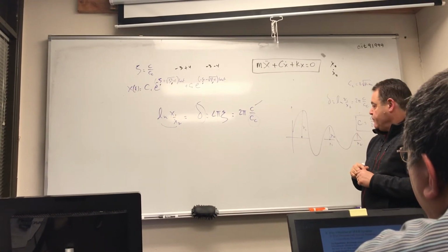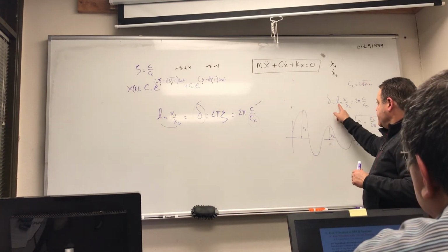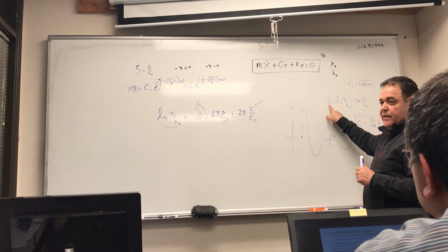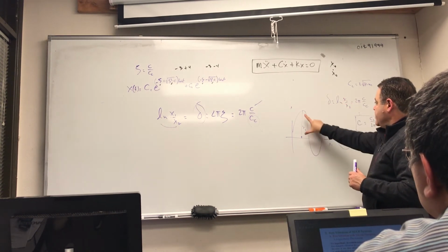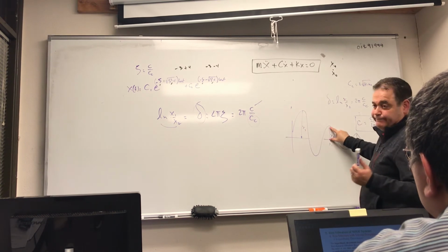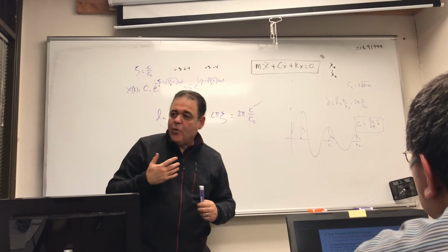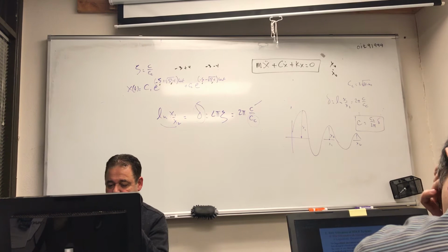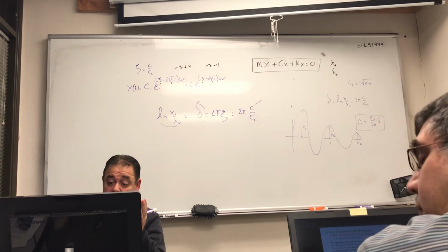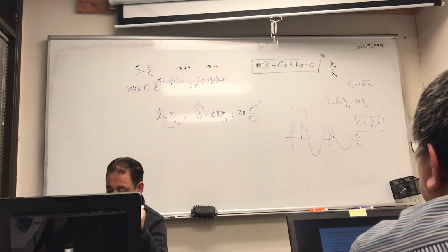What is delta on that graph? It's meaningless, it's just a quantity. It's just a rate, the log of this divided by that. So it's not something that you can show on the graph, and it's not a dimension by any means. But it's a very important thing that is done in vibration, because that's one way you can actually measure the damping of a system.